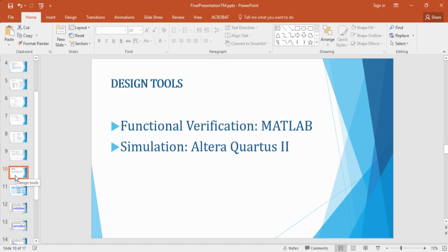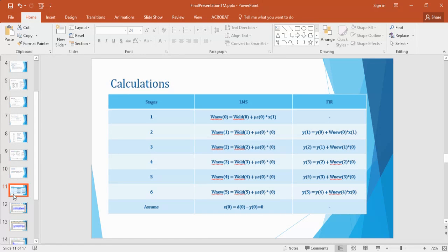Then after this, the operations of the LMS algorithm and filtering take place along with delayed inputs, which are multiplied with the coefficients generated using the LMS algorithm. For example, if you have a 4-tap filter, 4 inputs are multiplied along with coefficients to give the output, and all 4 outputs are added to give the valid output. Some of the calculations look like this.